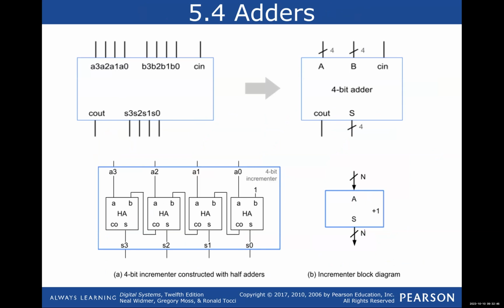So this is how the IC is built, but this is for the other classes; they build it hands-on. The IC chip already has 4 full adders built in inside it, so that it allows you to add 2 numbers, each one of them 4 bits. Your carry input here is the original carry input of the first position. You can connect it to 0 or 1. And this is your 4 bits of the summation, and that is your carry out.